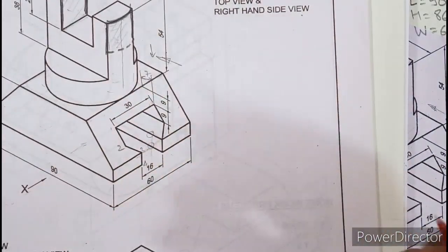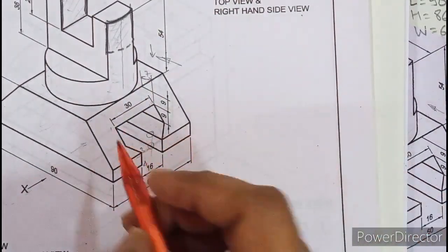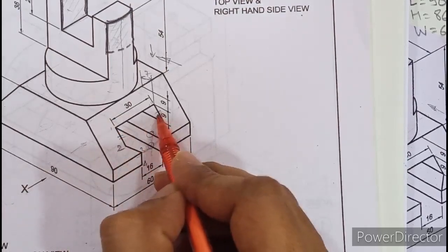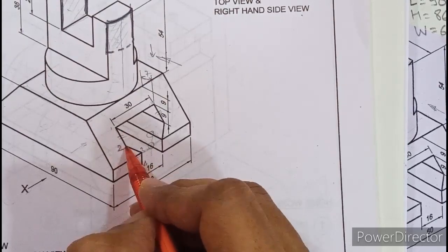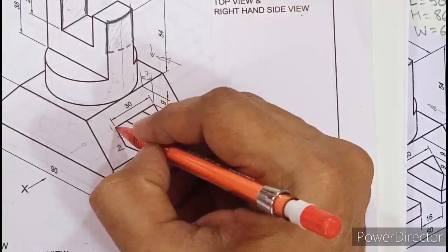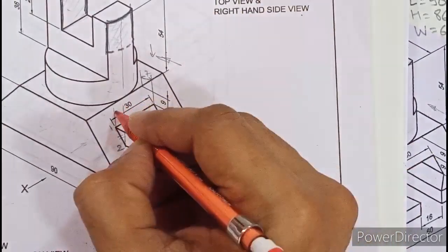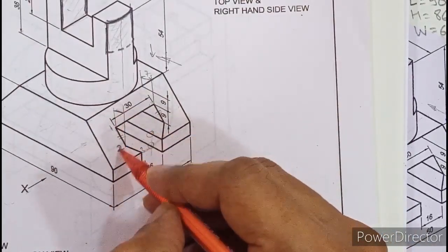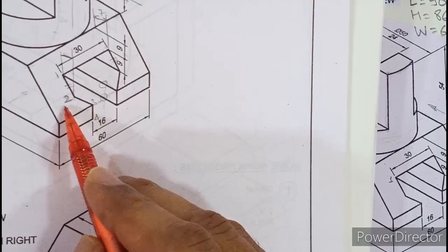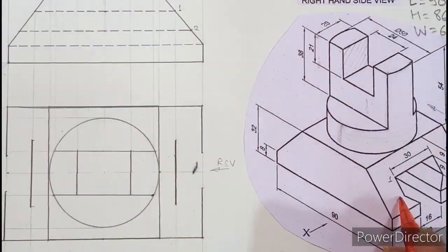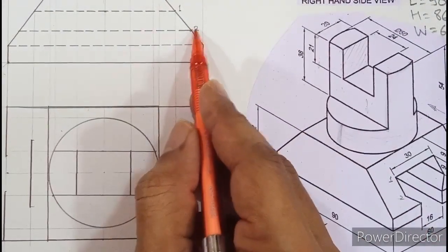It is obviously possible. Now from point number 2, you can see this inclined edge on the inclined surface from the top view. This edge will be seen apparent. So the length of the line 1, 2 will be seen from the top. Try to visualize from top, project 1 and 2, you can see a small line, isn't it? So 1, 2 will be seen apparent in the top view. For that we need to locate 2. So this 2 is same as this point what I marked. So see in this diagram, this point is 2, isn't it? The same 2 is over here, the hidden line.